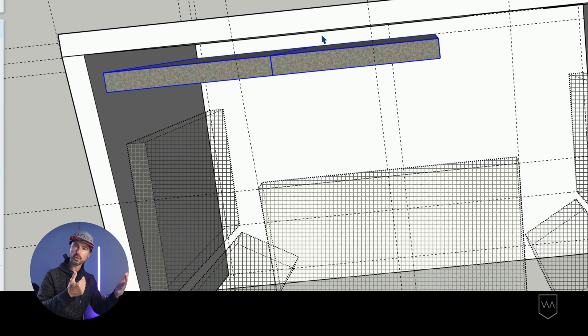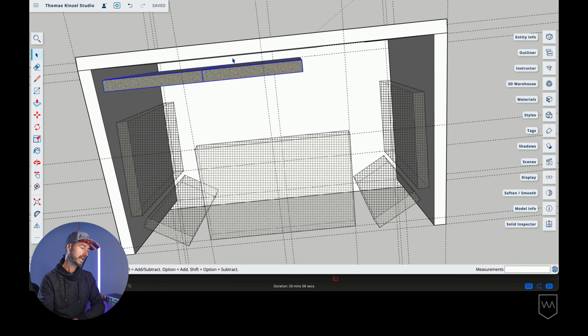So we are going to place the absorber closer to the wall, and we're going to use an air gap equal to the thickness of the module. So 5.5-inch module, 5.5-inch air gap. That means the modules are a total of 11 inches off of the back wall, and that is the absolute max we could eat up in this room without feeling like the acoustic treatment was impinging into the room volume too much. And that's going to be enough.